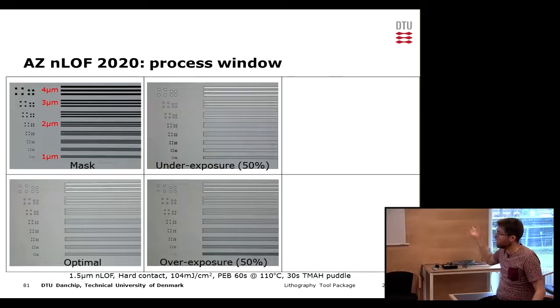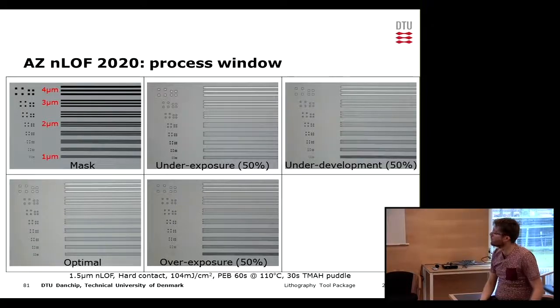So let's have a look at what happens with the development time. Keep in mind that the standard, the optimal development time here, what we see down there, is actually 30 seconds of development. So this is 15 seconds only, and you can see that the 4 micron structures are still perfectly fine.